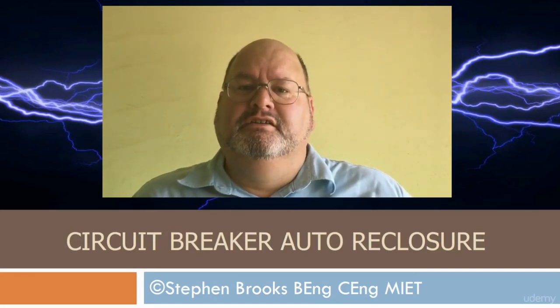When a fault occurs on the system, we trip the circuit breaker, then clear it. For certain types of faults on electrical systems, we sometimes want to re-close the circuit breaker to get the customers connected again. This principle is called auto-reclosure, and in this section, we'll see how this can be achieved safely and in a controlled way. By the end of this section, you will understand the sequence of events that occur during a fault, and see how timers are used to auto-reclose the circuit breaker to ensure that the customers are reconnected as quickly as possible.